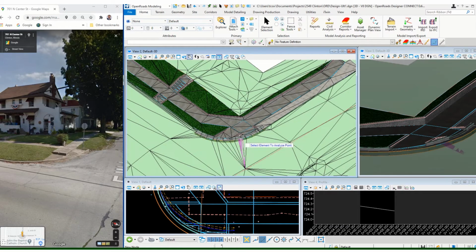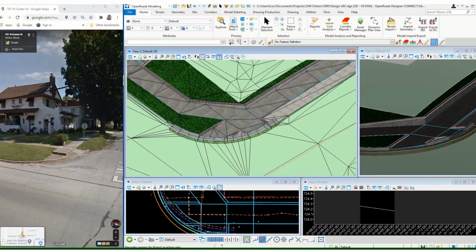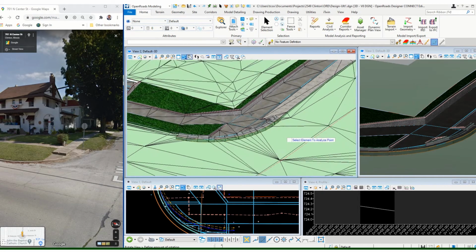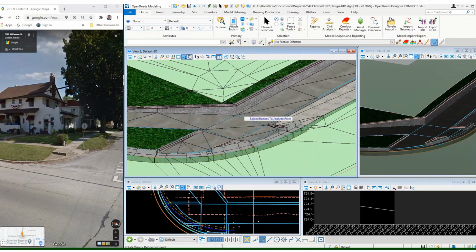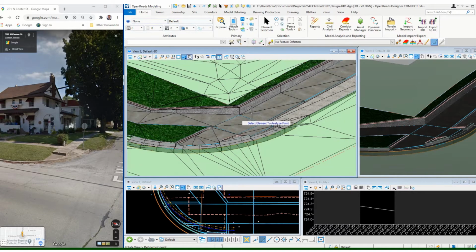Of course, one of our biggest challenges was dealing with this side street that is at 6%. So the way that we do that, and really what you're aiming for in the beginning here, is to get that 5x5 turning space, which is located right here. So the way that we're able to do that is once we get that existing profile along the existing pavement identified, we can apply the linear template and place this B612 curb and gutter, and then include the depressed areas, and then we're going to build off of that.